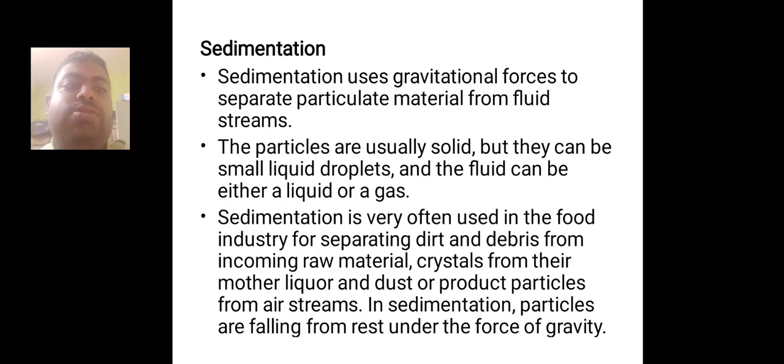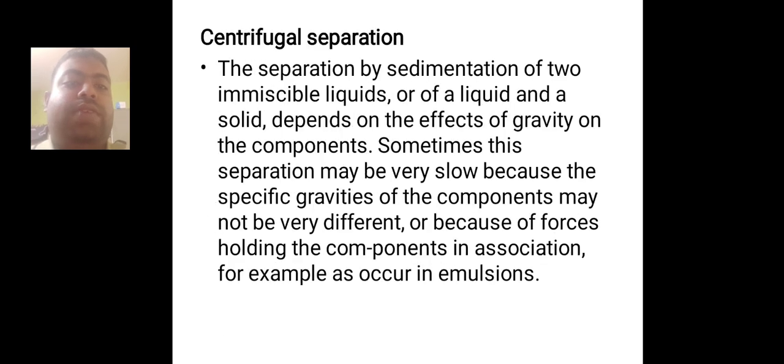Sedimentation. It uses gravitational forces to separate particulate material from fluid streams. The particles are usually solid, but they can be small liquid droplets, and the fluid can be either a liquid or a gas. Sedimentation is often used in the food industry for separating dirt and debris from incoming raw material, crystals from their mother liquor, and dust or product particles from gas streams. In sedimentation, particles are falling from rest under the force of gravity.